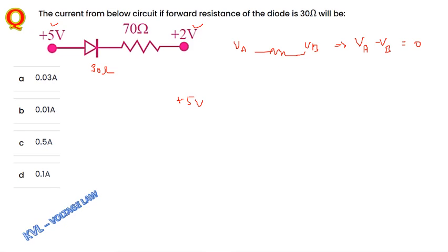Now see, in this case this is about the electron. Electrons will be moving from negative to positive, so this is the electron movement, so that the current will be moving from positive to negative. Hope you remember this one, this is the resistor, and this is the current flow direction. Once you measure the potential, that is V here, we measure the potential in the clockwise direction. Hope you remember this from current electricity. In this case, this is the resistor, so the potential here is minus IR.